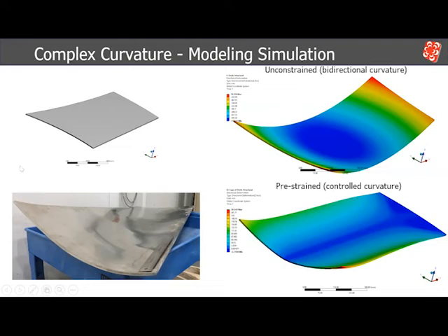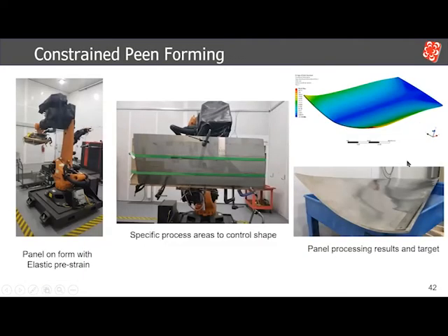But if we take our sheet here, this is approximately a 2 foot wide by 5 foot long piece of aluminum. Without any kind of laser peening correction, we'll simply end up with a bit of a dished structure. What we want to reach instead is a complex curvature. We have a flat surface at one end of the panel that then is gradually curved up to the other end. How we do that, our work uses simple toolings in this case.